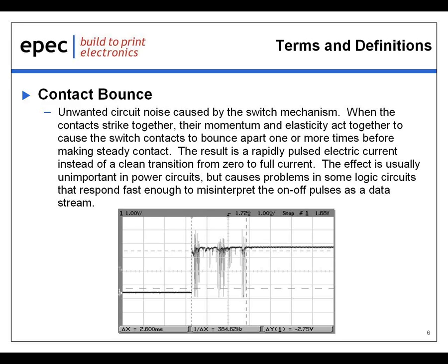Electronic circuits usually incorporate software debounce, but it has limits as well in avoiding problems with long contact bounce. Very long software debounce results in sluggish response from the keypad. High reliability keypads require low and controlled contact bounce times.